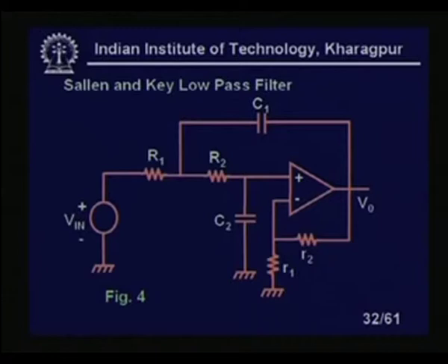So, this is the famous Sallen-Key low pass filter, which uses a single amplifier structure where we need 4 resistors. These 2 resistors, small R1 and R2, have different values and determine the negative feedback. This is your RC network, so it is a positive feedback topology because the RC network is in the positive feedback path.